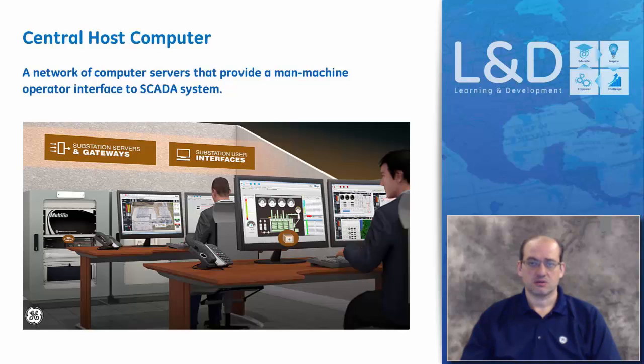Now, depending on the size and layout of the substation, the local substation might have its own HMI that would allow the engineer to look at the layout of the SCADA internal to the substation and information that would assist the dispatched person in resolving the issue at the substation.